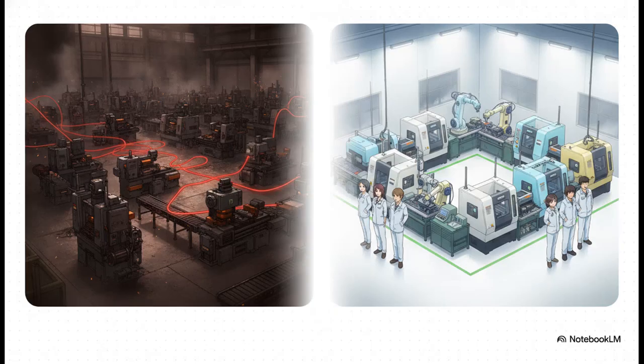The contrast in strategies here is pretty stark. To eliminate this waste, we must fundamentally rethink how we arrange our equipment and completely abandon that traditional process layout, where parts travel miles between isolated departments. Instead, our next crucial control strategy is to execute a cellular layout. This means we mandate that sequential operations are placed physically adjacent to one another.